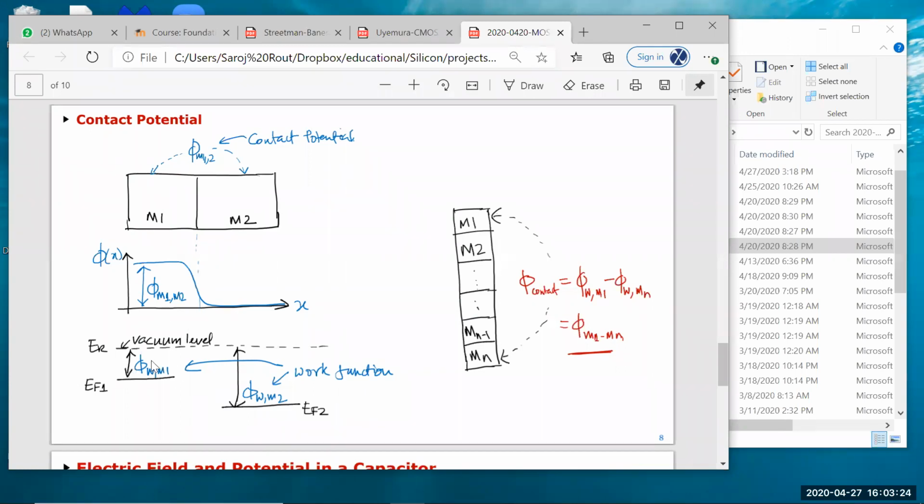So the work function is always the same, but for example, Fermi potential, in some books it's intrinsic minus the Fermi energy. In some cases it's Fermi energy minus intrinsic. They're a completely opposite sign, and there is no standard for it, unfortunately. So you just make sure you understand it from a material and a voltage perspective.